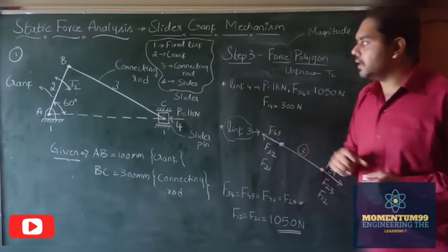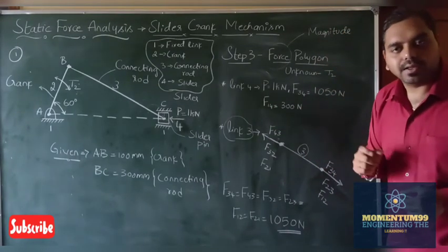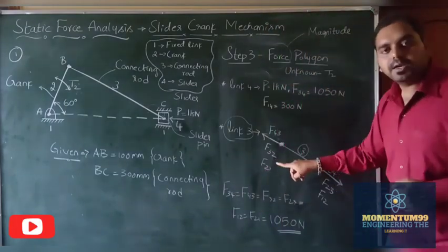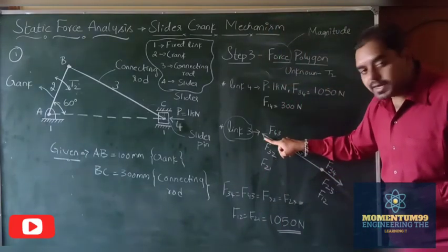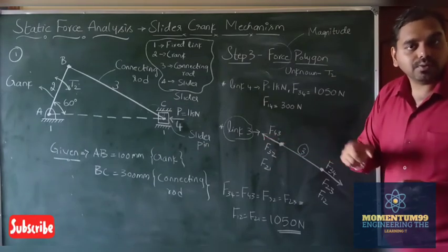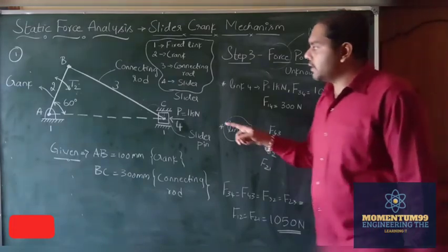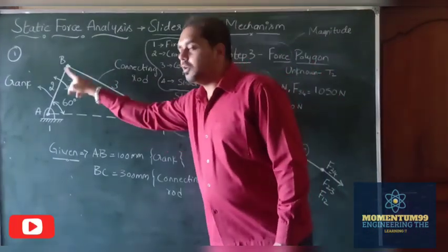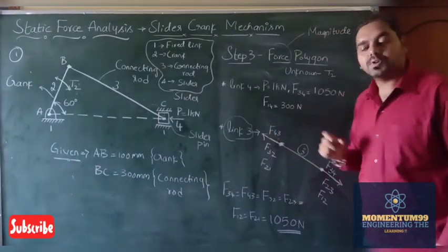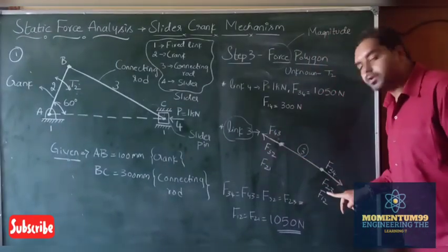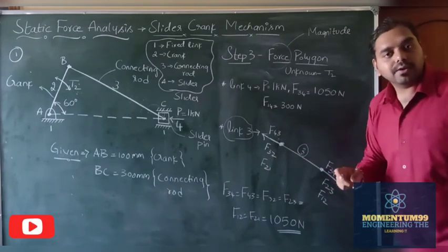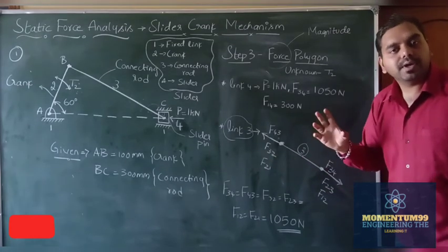Now let's learn the interactions between the second link and the third link. Considering links 2 and 3, we have this force F32. Again, the arrow indicates the force moving away from link 3 towards link 2, the 3-2 interaction. Whenever a force is transferred from 3 to 2, we need another force to counterbalance it. This force is represented by F23. F23 and F32 are equal in magnitude and opposite in direction. Hence the body will be in equilibrium.